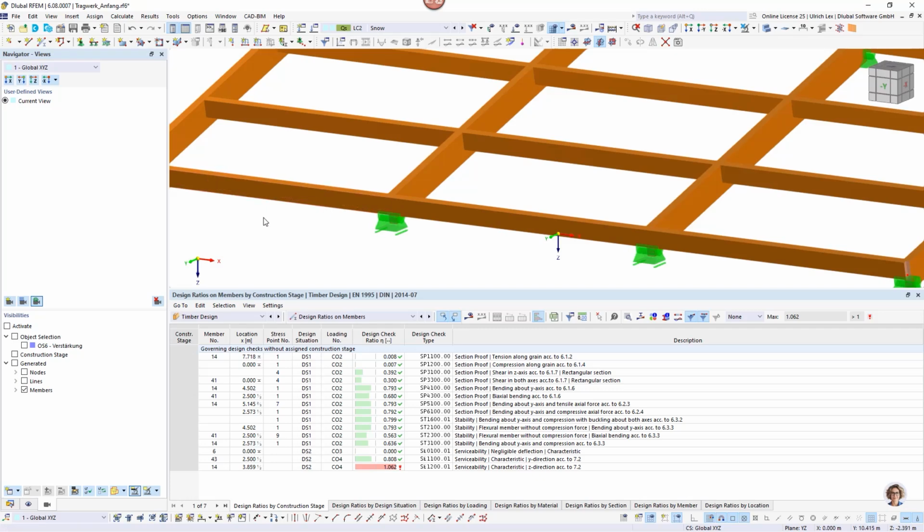Maybe we could try to create 2 additional beams on the right side and on the left side of this main beam and screw them together, and so strengthen this beam so that this additional load would be possible.